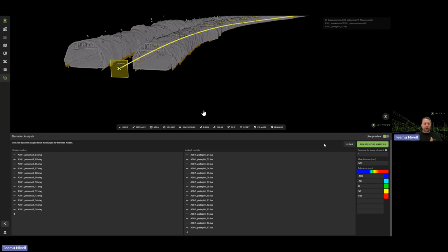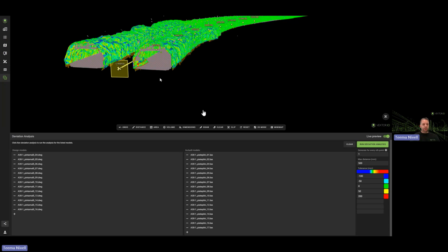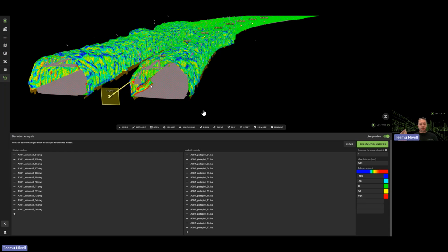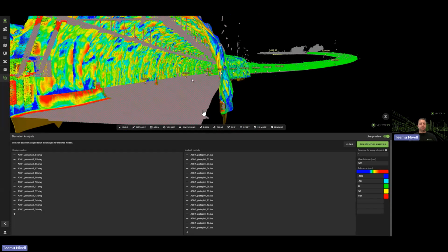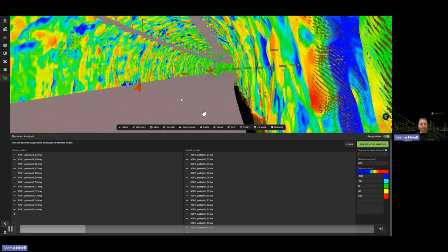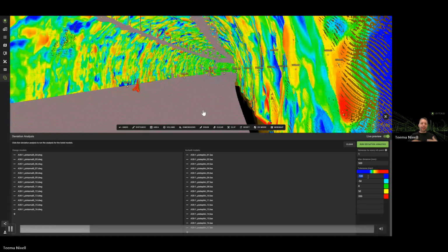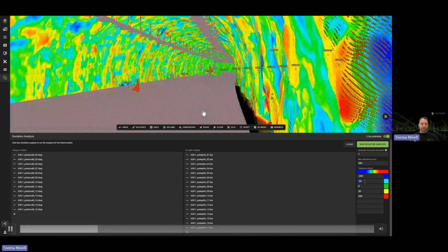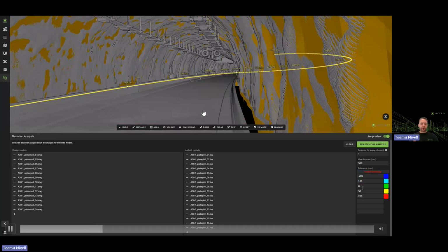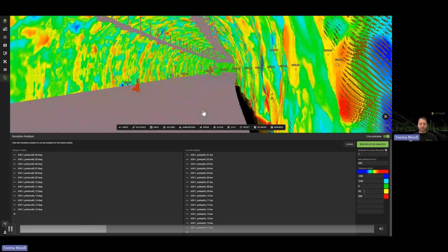You can see here on the left-hand side you have a design model, and on the right-hand side you have a list of the multiple LAS files. And you saw that we can switch on so-called live preview, and you can instantly see the result: what is out of tolerance and what is within tolerance, with the heat map. And you can adjust the tolerances, multiple tolerances, here.